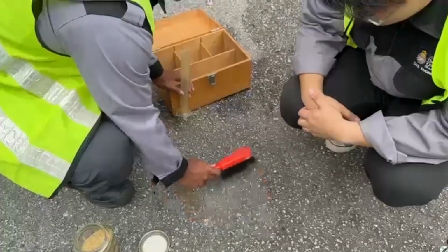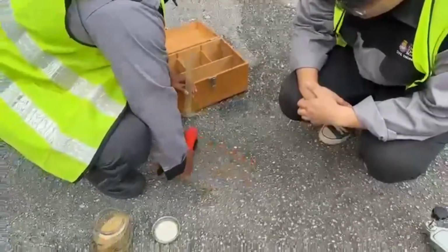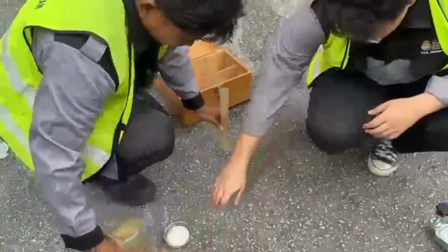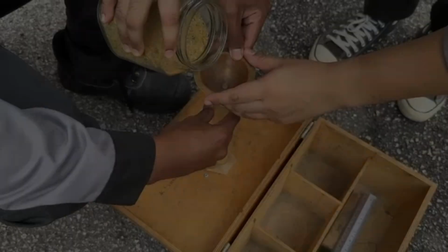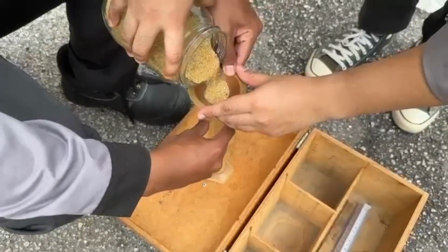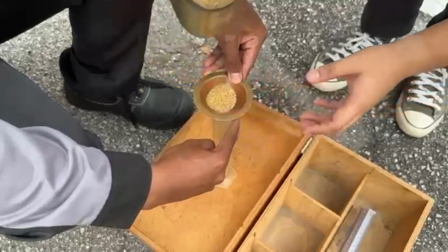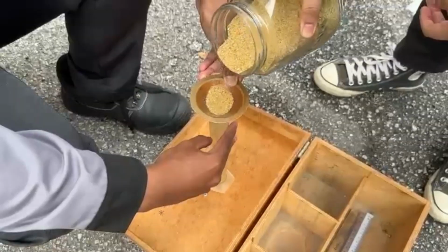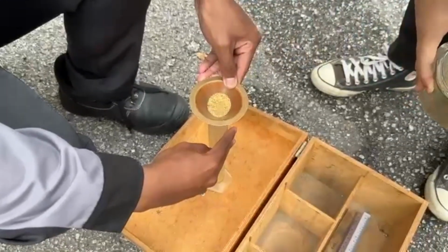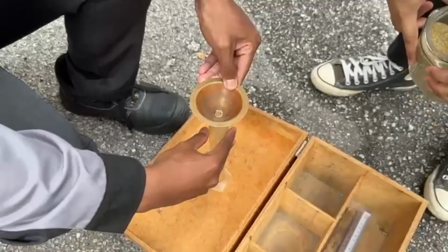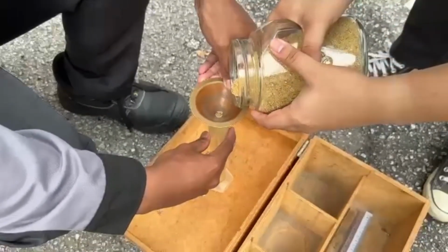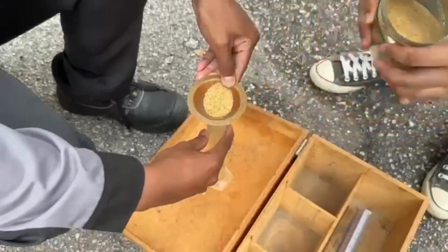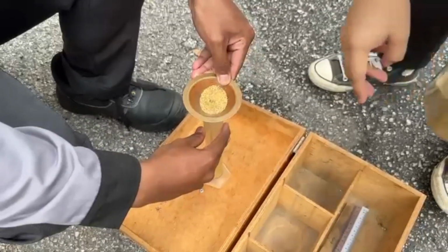To measure the pavement macro texture, we follow the sand patch method. First, we ensure the test surface is dry and swept clean of any debris. Next, we fill a standardized cylinder with a known volume of sand, in our case, 20,000 mm³. We pour the sand onto the surface and use a flat spreading tool to carefully spread it into a circular patch, ensuring the sand fills all the surface voids.